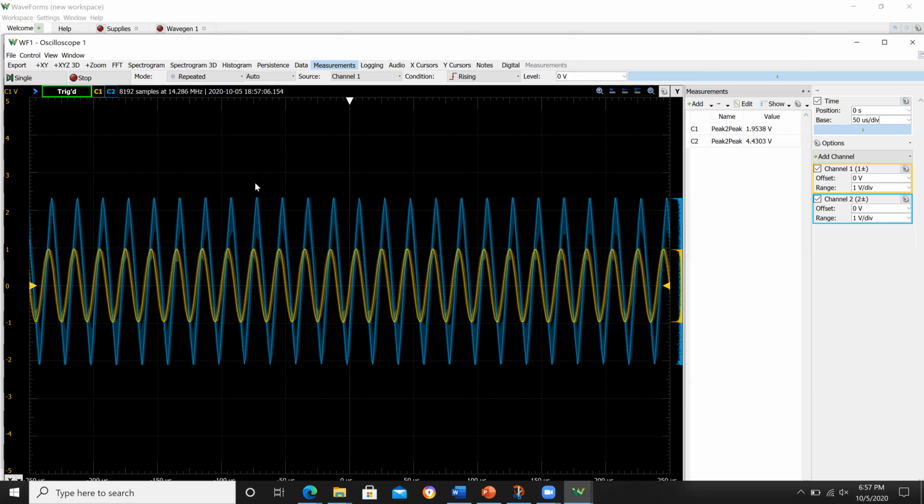So when that can occur, when the output hits a limit, much like the supply hits a rail, in this case, it hits a current rail on how much current it can source or sink, then you see a linear rise up and a linear fall down. So that's another one I just wanted you to pick up on right now. Let's see. I think at that point, that's good enough for tonight to conclude this session.